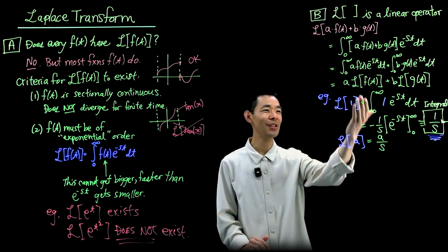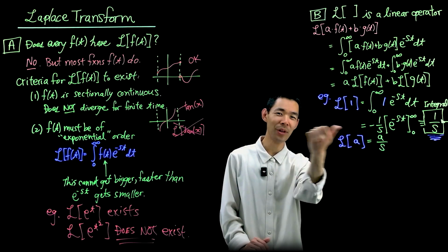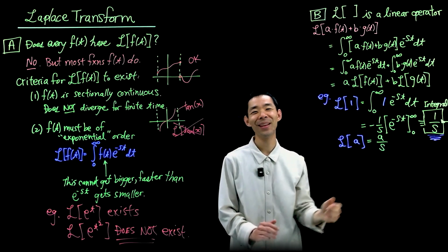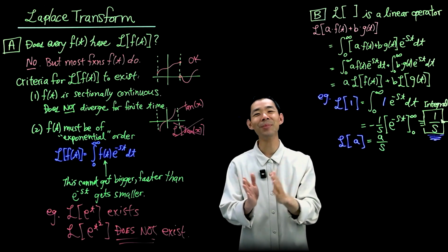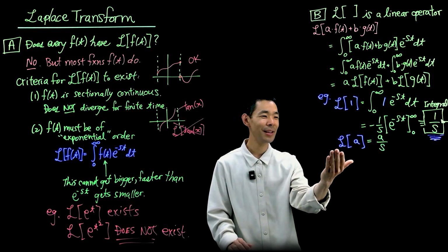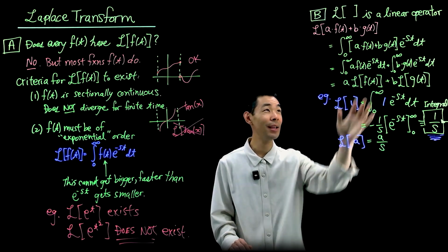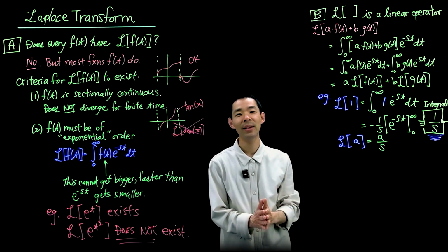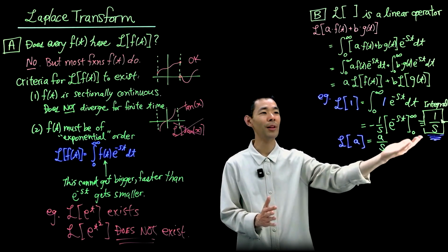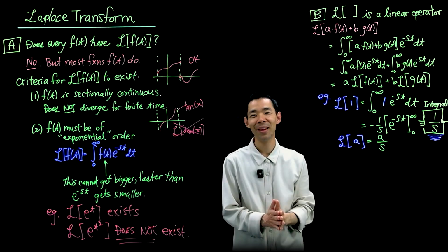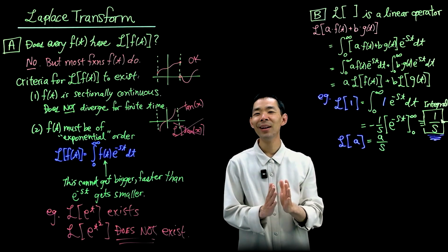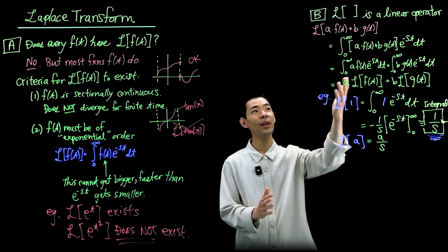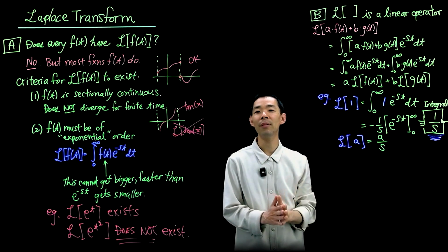Because the Laplace transform of some input signal coming into a block is just simply equal to 1 over s. And so it all comes back to Laplace transforms. And using the linear operator property, the Laplace transform of a is just a constant out in front times 1 over s, which is the Laplace transform of the function 1. Okay, one more little mathematical trick that you can use to figure out little tiny operations of Laplace transforms.